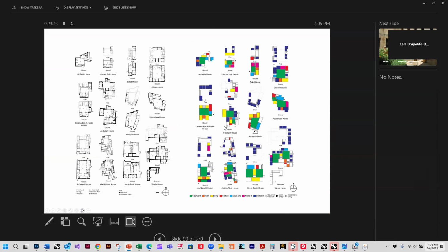They have a hot courtyard and a cold courtyard, like I was saying before. The hot courtyard gets sun and is open in the direction of the sun and is wide and big. And then there's one also that has water in it and a fountain, and that cools the air down. And the two of them in dialogue can create a thermosiphon and move the air back and forth.